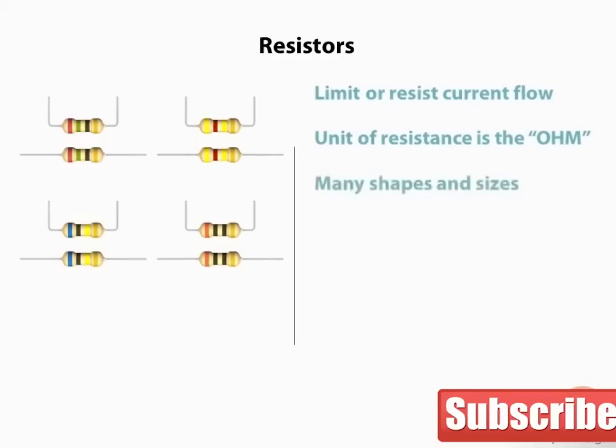Resistors come in many shapes and sizes. Other form factors are surface mount and through-hole configurations. You can find resistor arrays on a dual inline chip package or single inline packages. The type of construction of a resistor is important too. Resistance values can vary from very small resistances such as 1 ohm, and technically 0 ohms is not a resistance, but we can find resistors in 0 ohm packages. On the other end of the scale, we have resistors that measure in mega ohms or millions of ohms. The circuit and application determines the value we need.